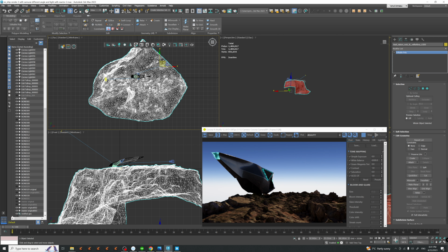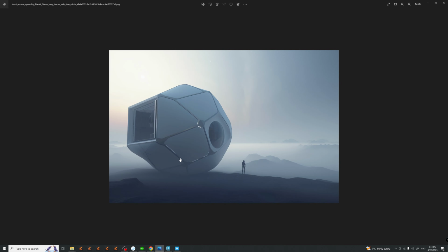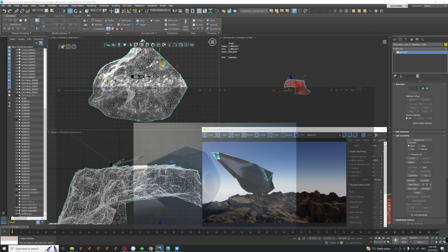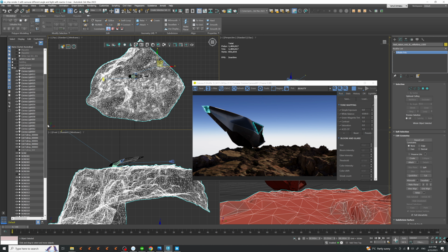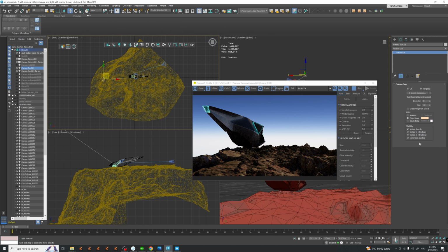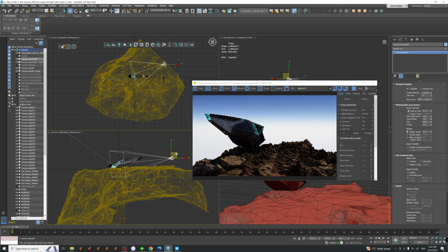We can do it in many, many ways, but I suspect that with the fog this time, we want to have two layers of fog. The first layer will be for the fog that is revealing the mountains, and the second layer will be just for the rest of the scene, just to use it for the sun. Now, another thing that I do want from the sun, because it's quite big. Yes, the size is 7, so I wanted to have very soft shadows, right? But I think we can set it at 0.3 because I do want to have some God rays at some point in time.